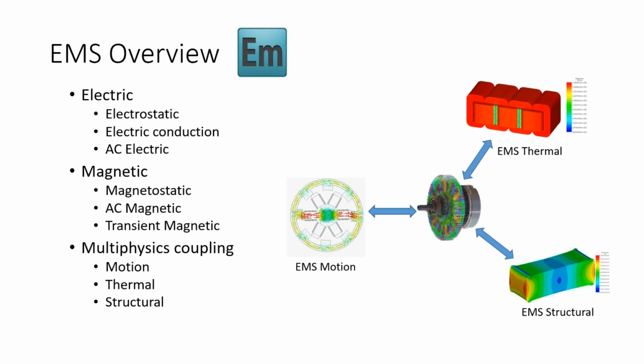Static modules allow you to analyze fields, inductances, capacitance matrices, torques, forces, etc. in static conditions where the field does not change, where you have maybe DC current or permanent magnet excitation, or in electrostatic you would have a fixed constant charge distribution in your assembly, or fixed potential levels on different parts. So for these cases, you would use either electrostatic or magnetostatic solvers, and their main applications.